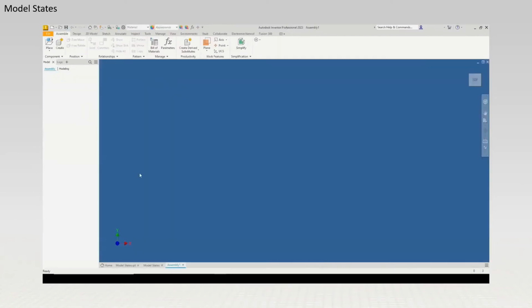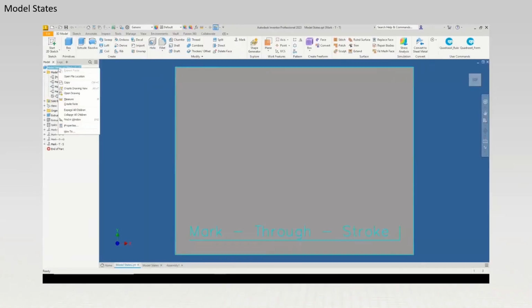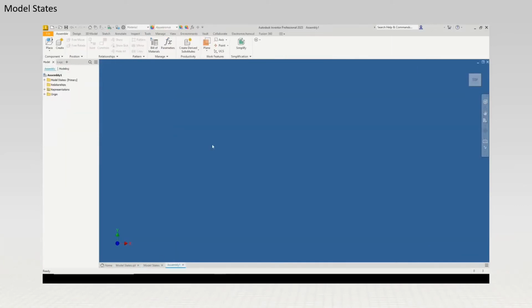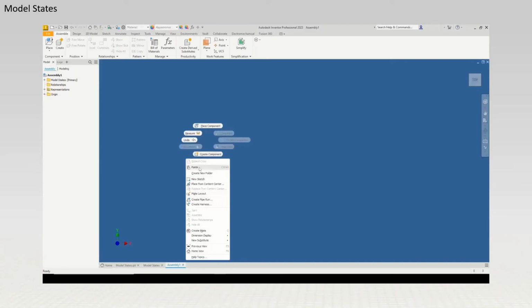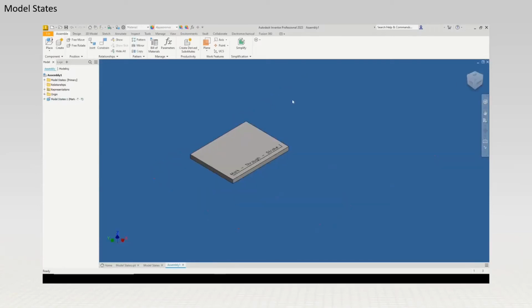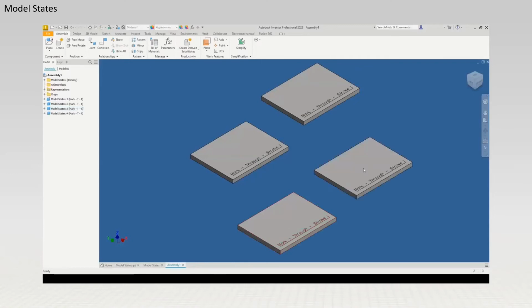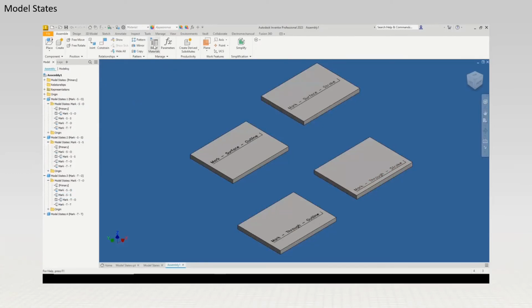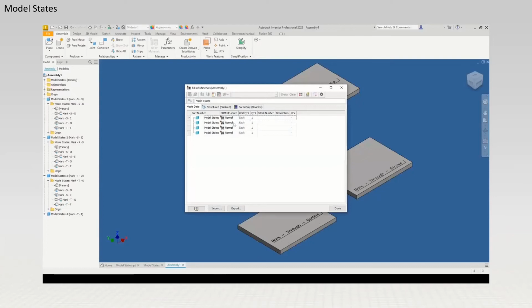If we add these model states to an assembly, they're all being pasted using whichever option I've currently got active. Then we can expand each node in the browser and just a quick double click, and you can see there we can swap out model state A for model state B. I also feel that sometimes it's a little bit quicker because we're not having to load files off the hard drive. They're all the same part, they're all model states.ipt.